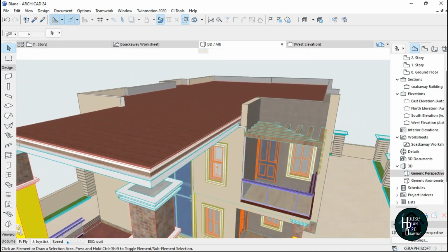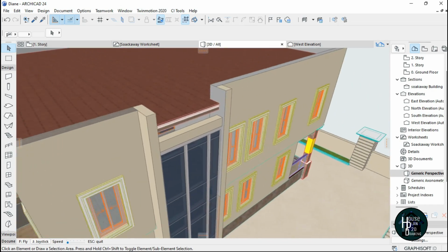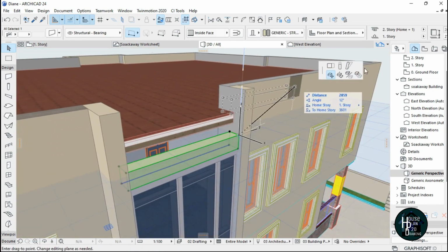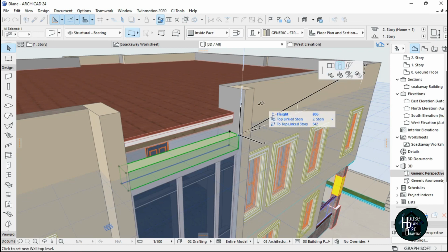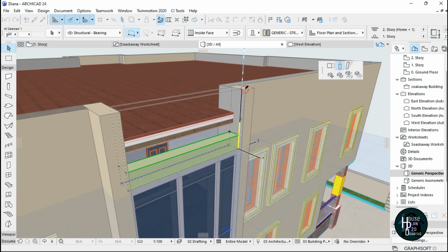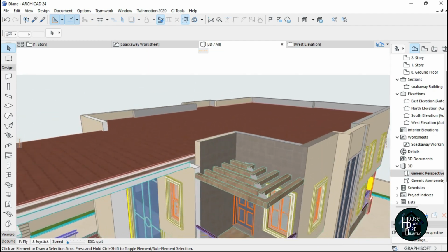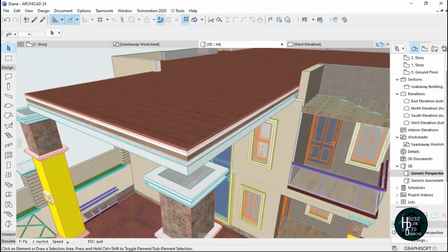So now I'm going to raise this one up too. I'm going to click on it, click this node here, select this stretch height, hold down shift and click. So it's going to form that straight line. Okay, it's going to merge with the both. Now for this other one too, you're going to do the same thing.